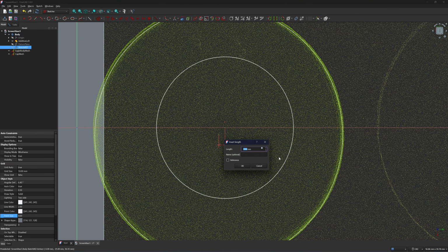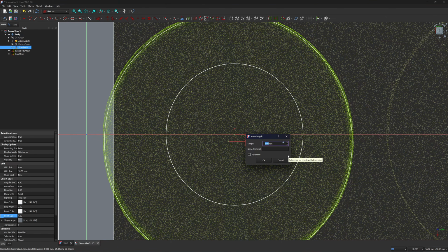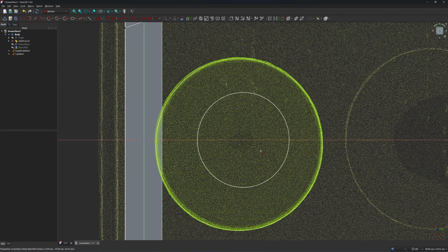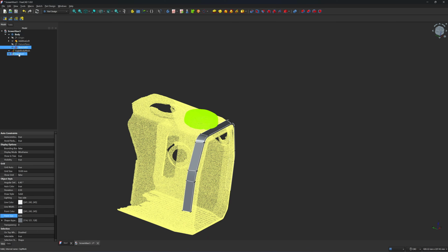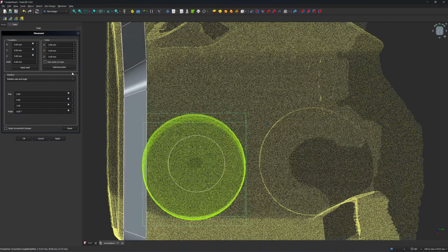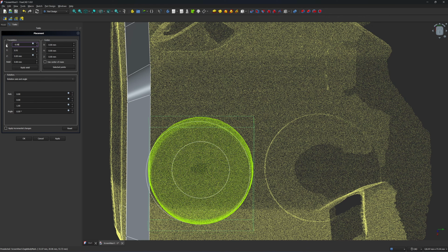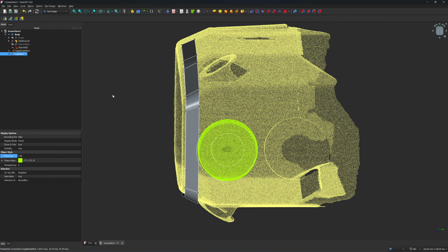So it's 0.91 along the y-axis to the right, and it's 0.98 along the x-axis going up. So I'm going to change the cap position. Click on close, click on cap, right click, placement. So it's 0.91 and minus 0.98. Okay, now the cap should be in the center.